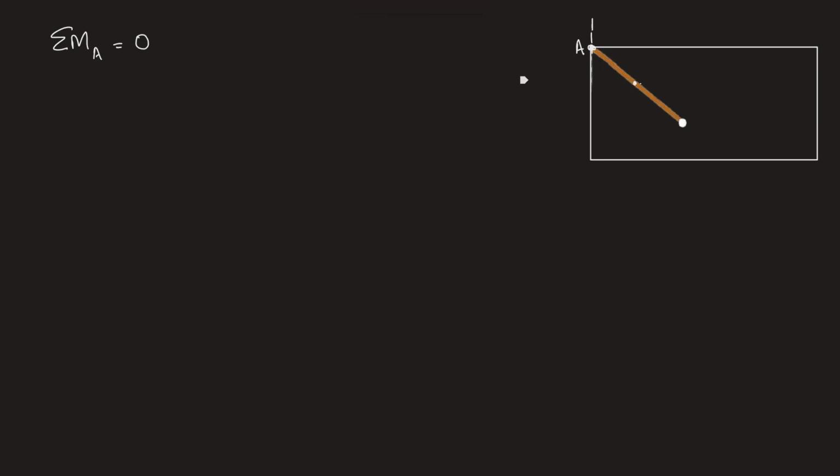Now let's say weight of the rod is going to act at CG. So let this be WR, weight of the rod, this be WB, weight of the ball, and FR and FB be the buoyancy forces on the rod and the ball. Then we can write bending moment about point A as anticlockwise taken positive. So FR into this distance here is X and this one will be 2X. This one will also be X because weight acts at the center of the rod.